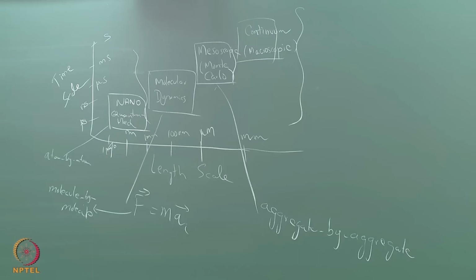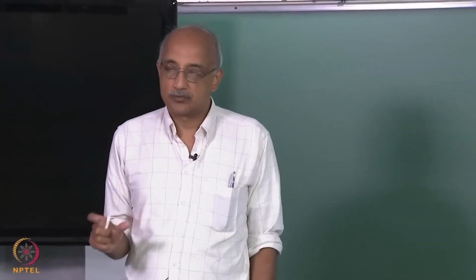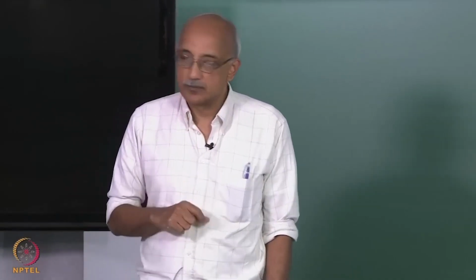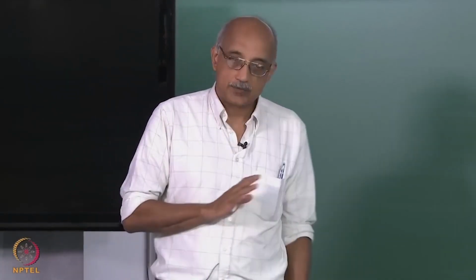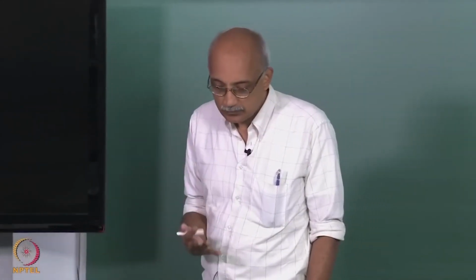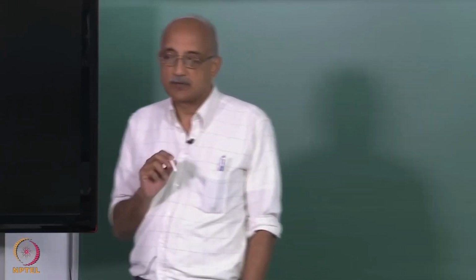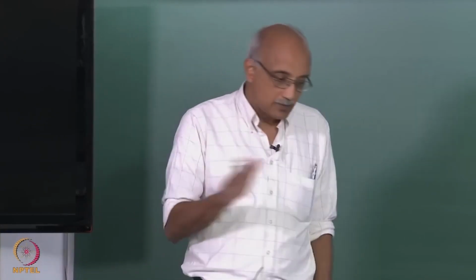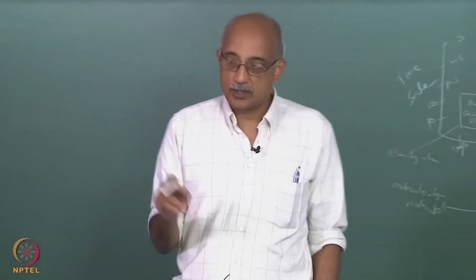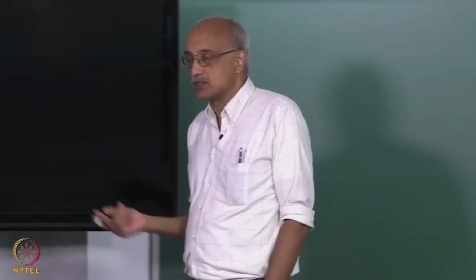So, in this regime you have now formed films or aggregates that are of the order of a few microns, and you start trying to understand how these aggregates behave. Typically this is done using Monte Carlo simulation techniques, using probability theory as well, because the laws that govern how attachment of individual atoms and molecules to form larger aggregates happens cannot be deterministic in nature.